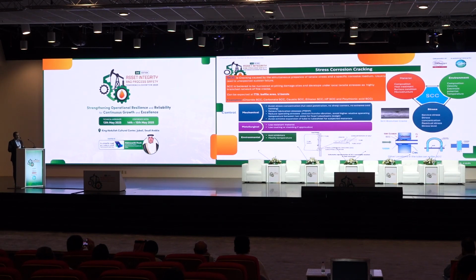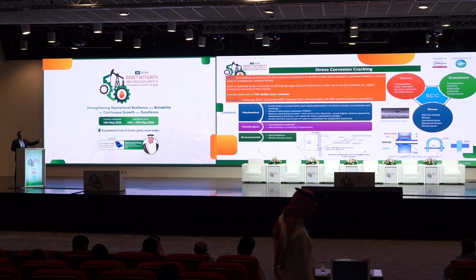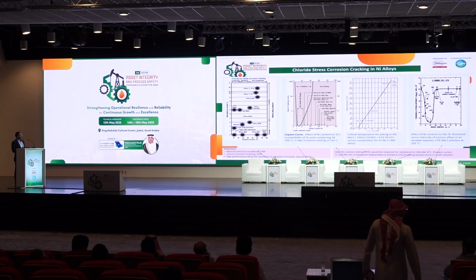And stress corrosion cracking occurs at locations of high localized stresses, especially if stress relief is not applied at the U-bends, or at the location where you are doing the expansion of the tube to the tube sheet. As you can see in the figure here, if the expansion extends to the edge of the tube at the tube sheet from the back side, from the shell side, you can create a very high localized area of stress concentration, which might be an area for attack later.